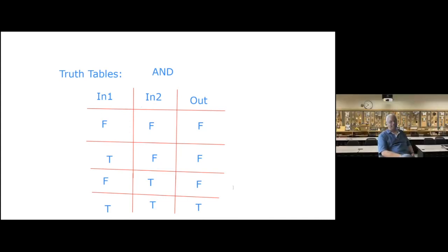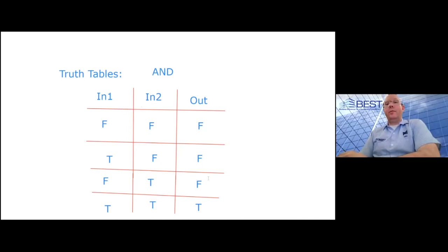That's a truth table. Really basic. You can look at all of the different inputs for basic Boolean blocks. If you want to get into more complex exercises, with multiple AND blocks or multiple AND and OR blocks and NOT blocks, it can be a really good thought exercise for the students. Just be careful about the number of inputs and blocks you use, because if you're having them do truth tables, the truth tables can become absolutely huge unintentionally because of that 2 to the n power